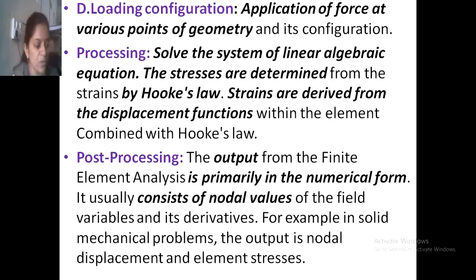Then loading of the configuration, so application of force at various points of the geometry and its configuration. After that, processing: solve the system of linear algebraic equations. The stresses are determined from the strains by Hooke's law. Strains are derived from the displacement functions within the element combined with Hooke's law.